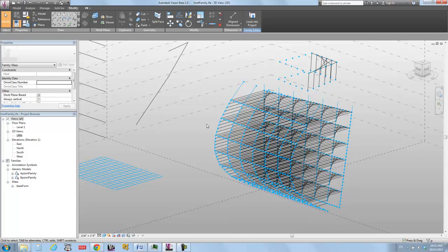I have a question. How did you get to show to hide that? Right, so that was the visibility graphics thing. So if you go to maps, you uncheck form. There you go. All right.